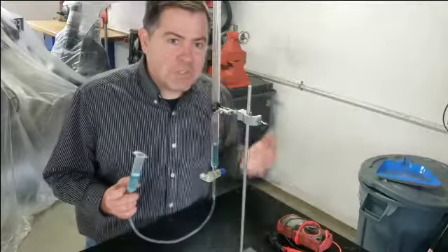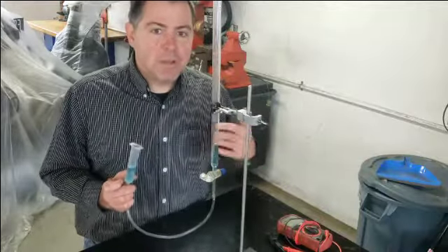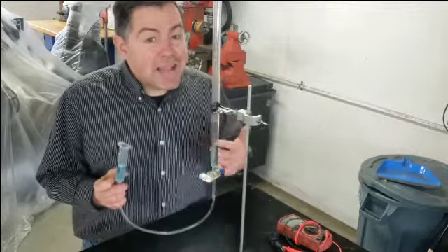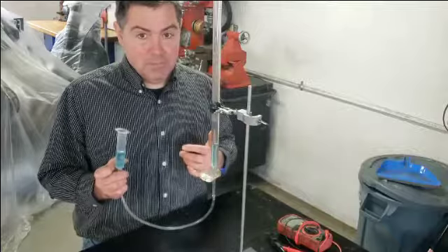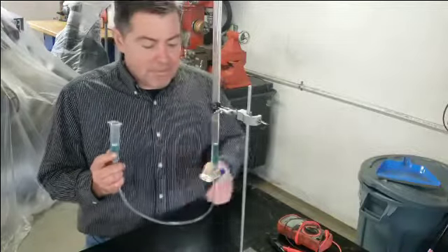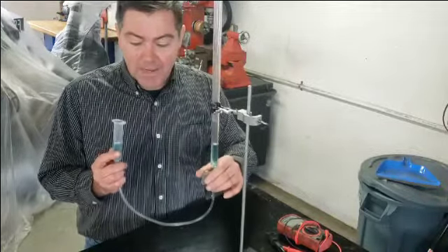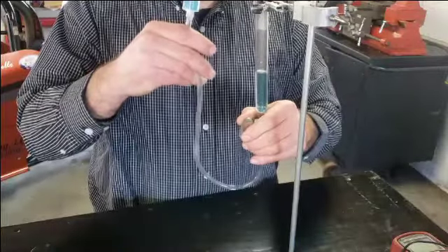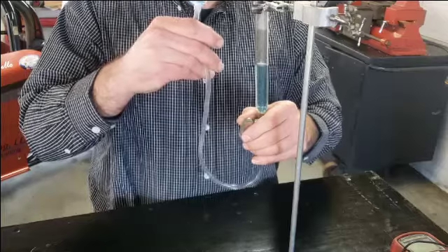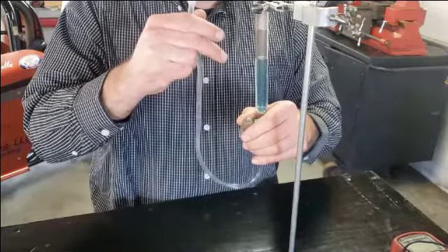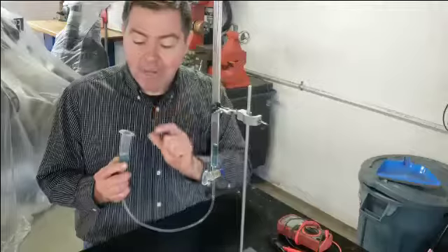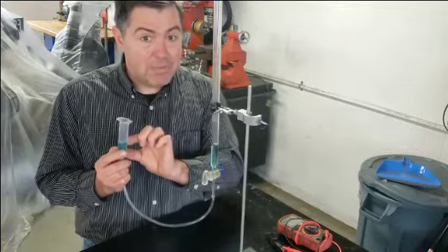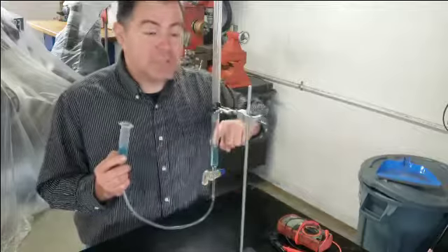That total resistance in that loop will impact my current flow through the circuit. Now, that resistance does not necessarily remain constant. To show you an example of this, I'm going to allow my fluid to flow again, and I'm going to raise this tube. As I raise this tube and the levels become similar, we see the flow of current decrease greatly. Why is that happening? Well, that's happening because I'm creating a potential in my secondary tube that's acting in the opposite direction.